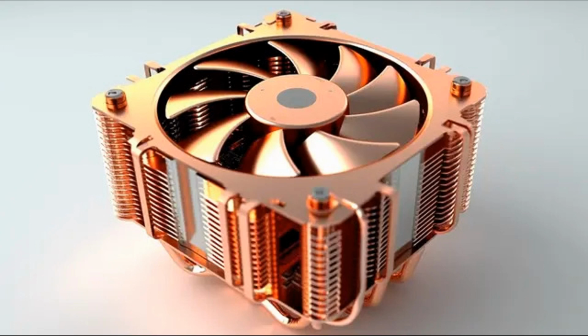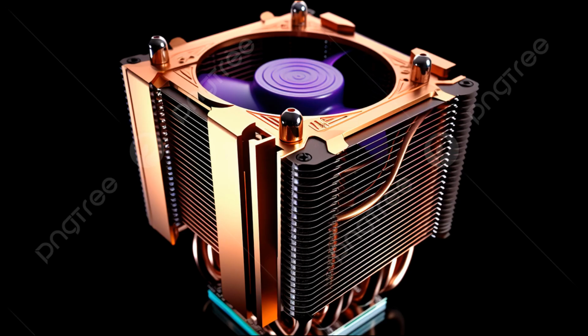Passive heat sinks are commonly used in a wide range of electronic devices and systems, including computers, laptops, LED lights, and power electronics. They are preferred in applications where noise, power consumption, or reliability concerns may limit the use of active cooling solutions. While passive heat sinks are generally simpler and quieter than active heat sinks, they may not be as effective in situations where high levels of heat dissipation are required. In such cases, active cooling solutions may be necessary to adequately control temperatures and prevent overheating of electronic components.